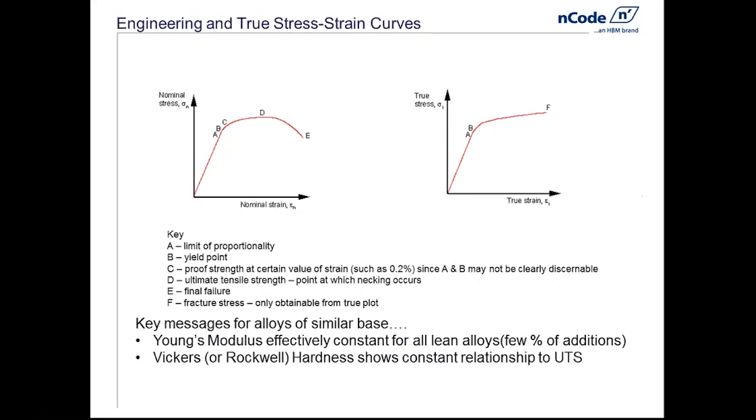Go back to a more familiar field from the engineer's point of view. What does this show up like if you deform it and measure the deformation properly, as opposed to just squeezing it and looking for the kinks? On the left, I have the engineering stress-strain curve, and you can see that in the region from the origin up to the letter A, we can move it, we can pull it, and it will deform up and down that, and it can return when you take the load off back to 0. But if we get past B, it will deform permanently. Very often, and this has been my own experience of test work, you cannot determine a clear yield point.